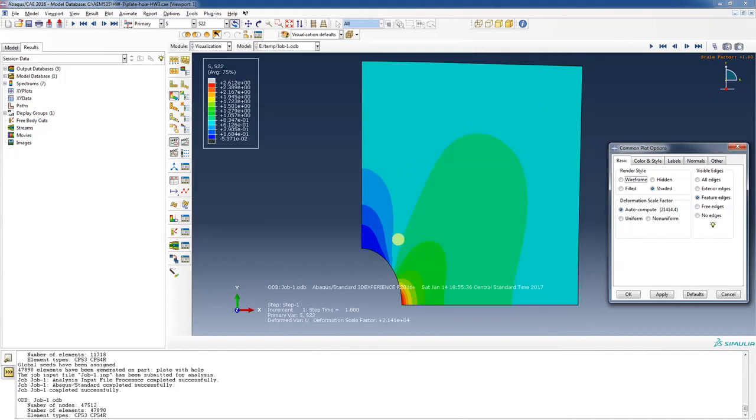And it's kind of interesting that the contour goes over into here. Right? And right around here, it should be pretty close to zero stress according to the theory. And it looks like it says maybe at this point it's around 0.168. We could probe that value and find out. Let's go ahead and do that.